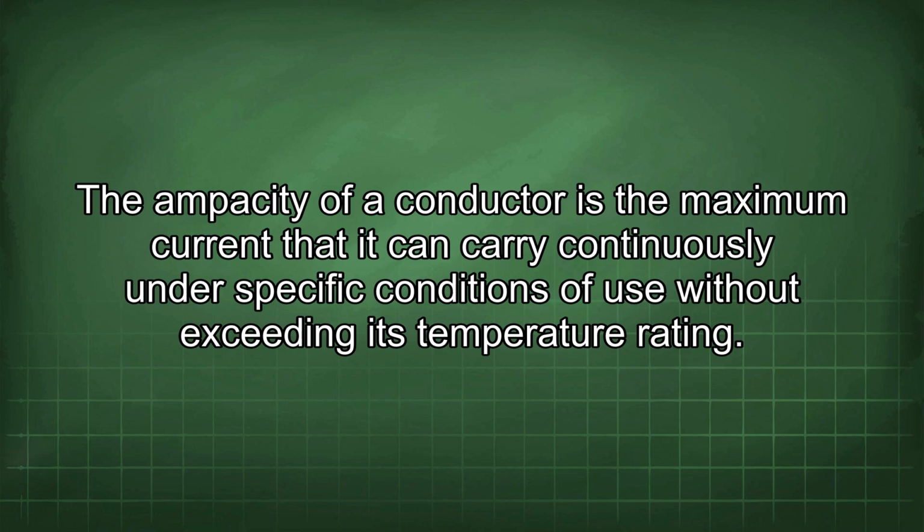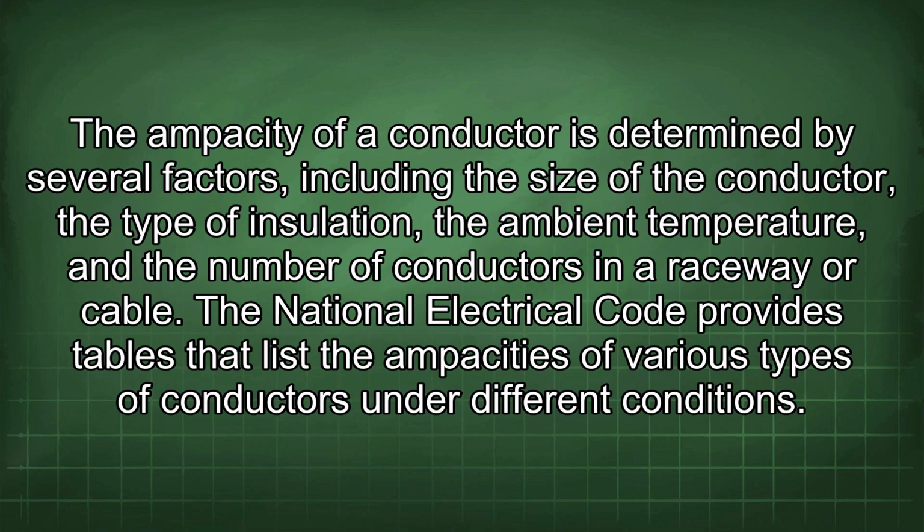The ampacity of a conductor is the maximum current that it can carry continuously under specific conditions of use without exceeding its temperature rating. The ampacity of a conductor is determined by several factors, including the size of the conductor, the type of insulation, the ambient temperature, and the number of conductors in a raceway or cable. The National Electrical Code provides tables that list the ampacities of various types of conductors under different conditions.